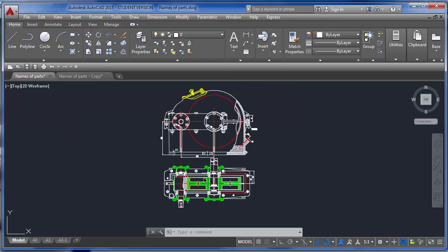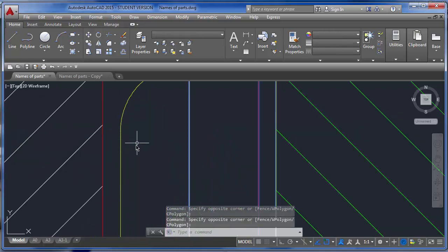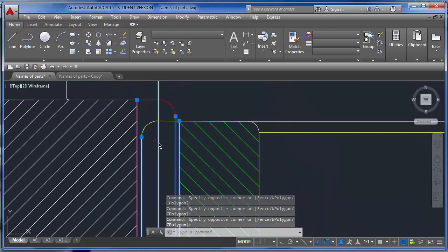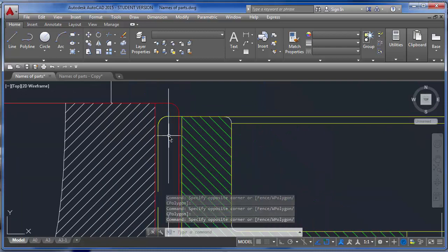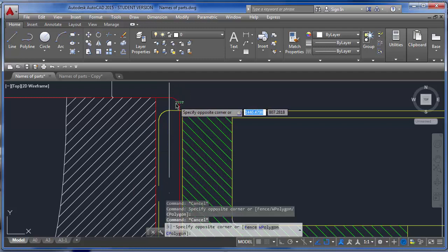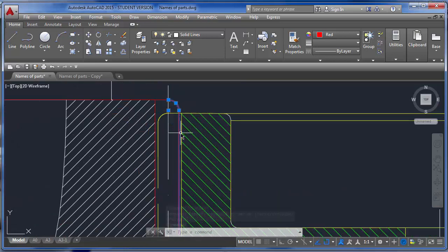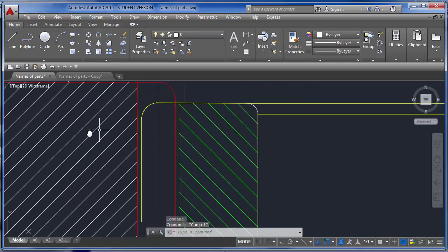I think now we're good to go. And here these 5 lines are really crucial because she actually checks a lot about this and people make mistakes here. What does this 5 line mean? This is the mating line, the imaginary center line. It's connecting here, and this is the outer part of the gear. Like this is the gear teeth, right? The end of the gear teeth of the small gear. This is the end of the gear teeth of the big gear.